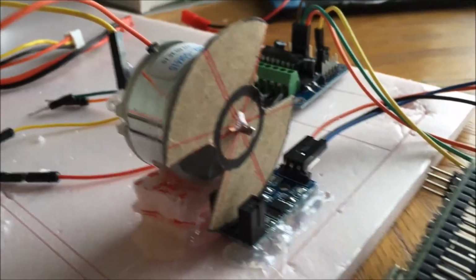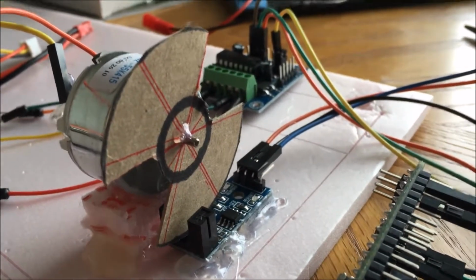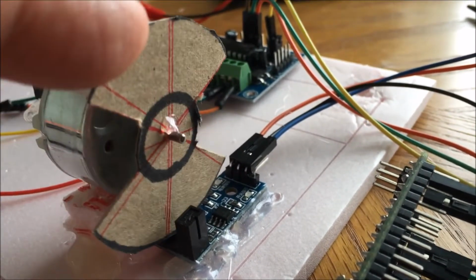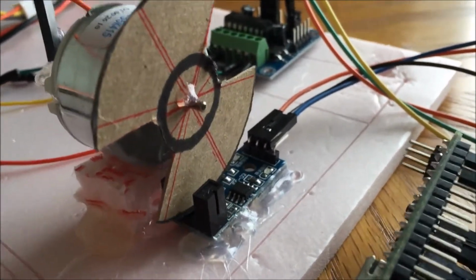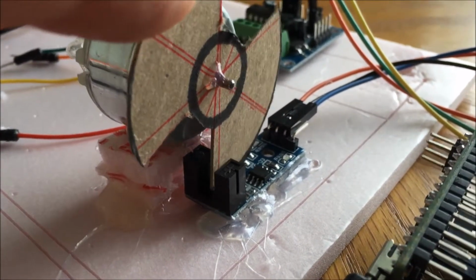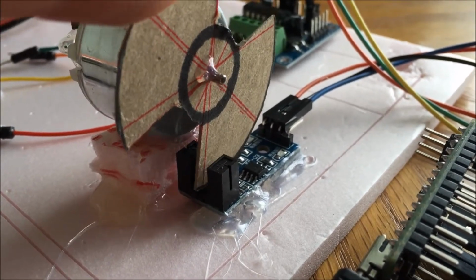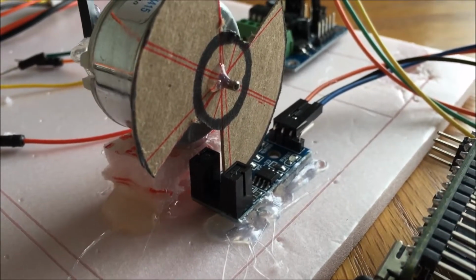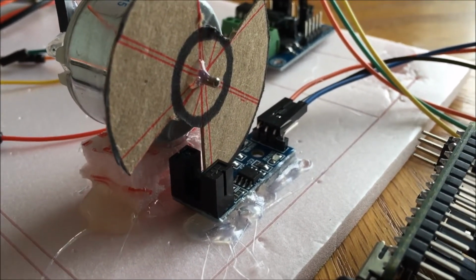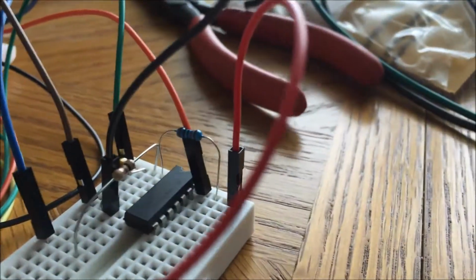But what was happening was I was getting 4 rising edges and 4 falling edges most of the time during one rotation. And all I could figure was this was due to the bouncing that can happen when you have a transition of a digital signal from 0 to 1 or 1 to 0, similar to what you get from a mechanical button. So I used the same type of circuit to debounce this, and that amounted to a